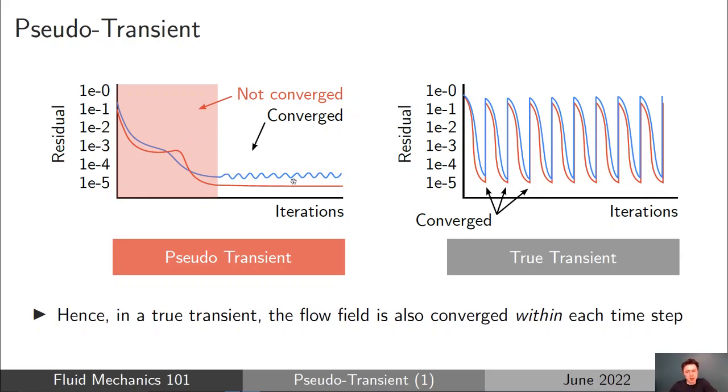but we have the converged solution at the end. Now, if you contrast that to a true transient approach, of course, the residual plots look very different and often they're very confusing, but they're likely to look something along the lines of this, where the residuals start high and then the residuals drop as we carry out those iterations of the equation within the time step.